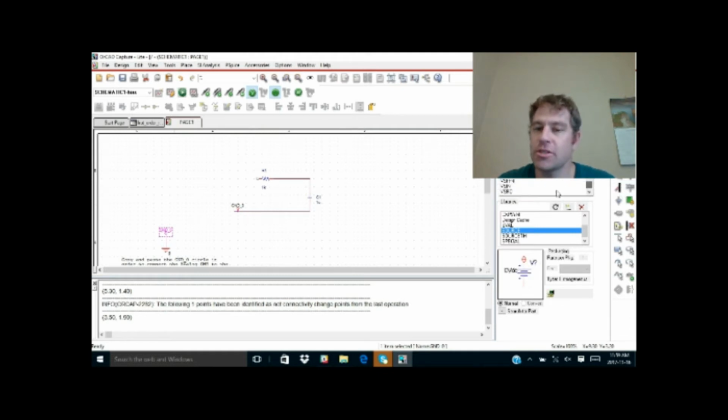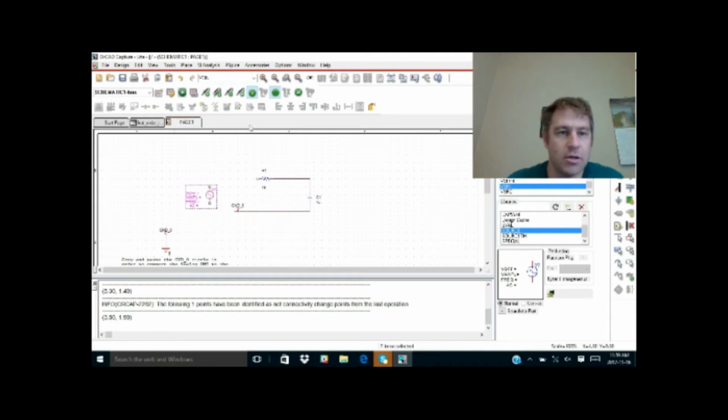Okay, so let's actually put in a sine wave. We're going to define the sine wave and its frequency. So I'm going to place it on my, I click it here, double click it here, and then I click it inside my project, inside my schematic. I'm going to wire the whole thing together, like this, and like this. Okay, so as you can remember, this is grounded, right?